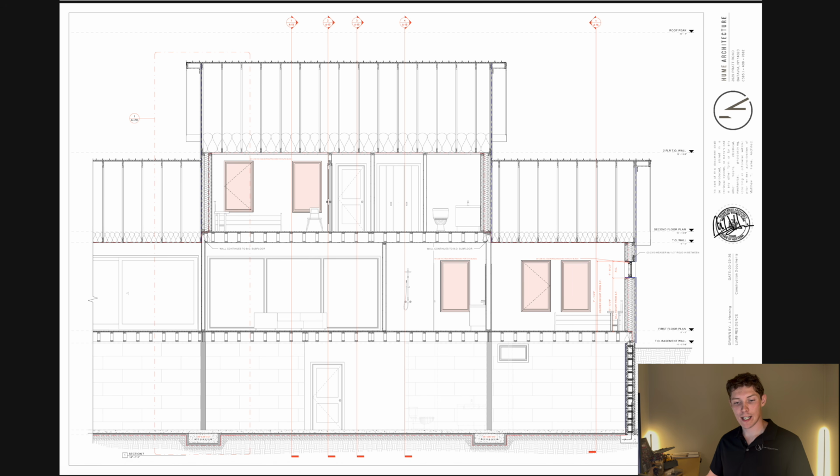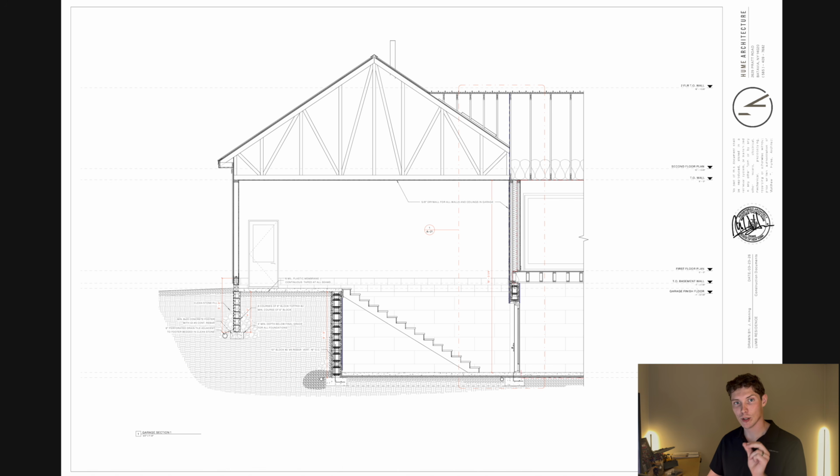As we go through the drawing set, the details get more and more intricate. We start with more generic sections and views and start going in and getting the exact construction technologies. So with this section, we've blown up the scale, which means we've made it a bit bigger, and we can see some more of those details. As we go through, you can see we have our different section cuts, and we have different callouts. These callouts zoom in on a particular detail that we want to show the contractor and the client to make sure everything comes together the correct way.